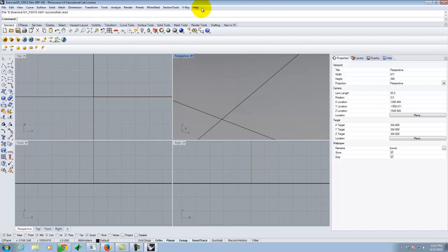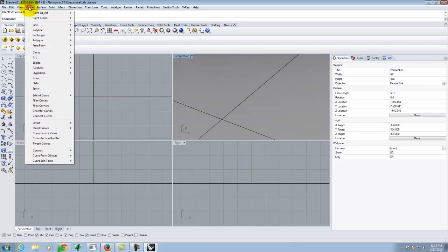In Rhino, there's usually two or maybe three ways of accessing a particular command. Almost all the commands are available through the menu structure. It's kind of a long, slow process to get there, but they are there. So if I wanted to draw a polyline, I can go to Curve and then to Polyline, and I can specify what kind, etc. So it's all there, available for me.